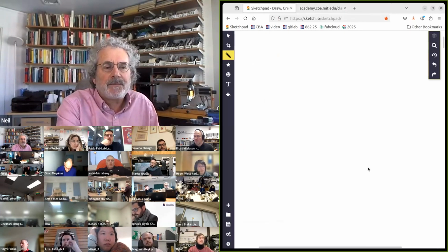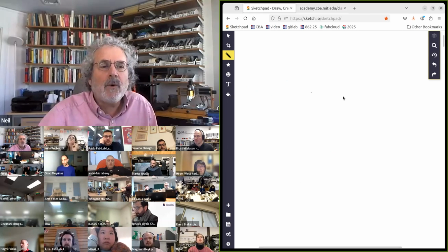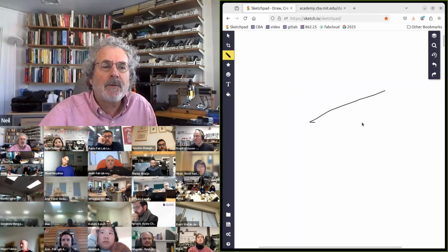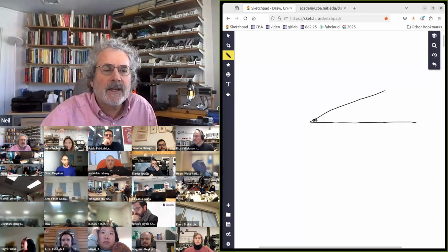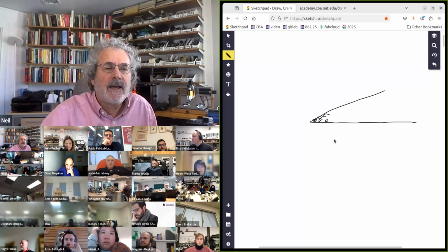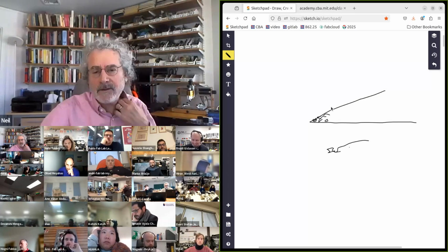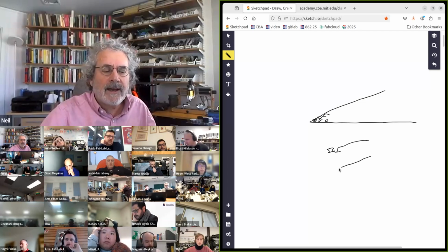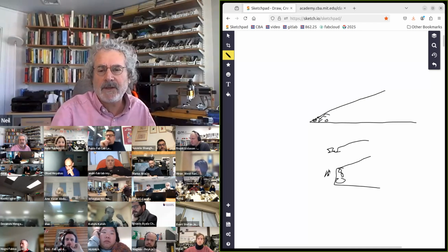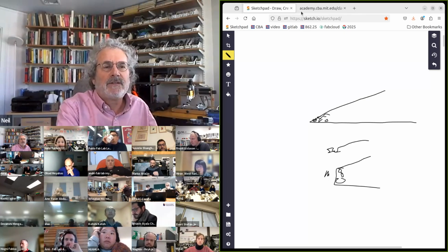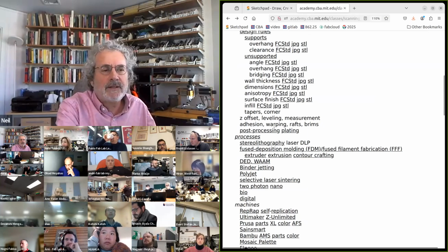And then you want to avoid a sharp corner like that. Because if you have a sharp corner, what you'll get is, say, one pass of the filament and then maybe two passes. And so when you actually print it, what you'll get at the end is sort of spaghetti. You want to have a face that has enough passes of the filament to give you a good interface. So just in the design rules, you want to avoid sharp corners.